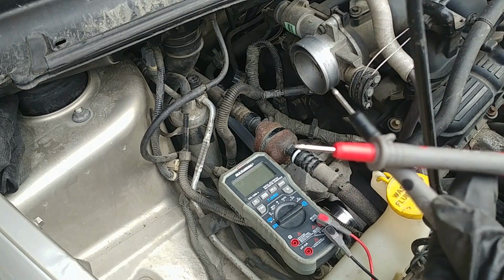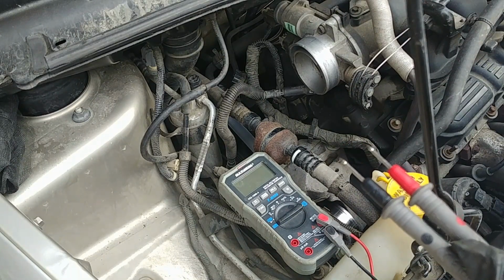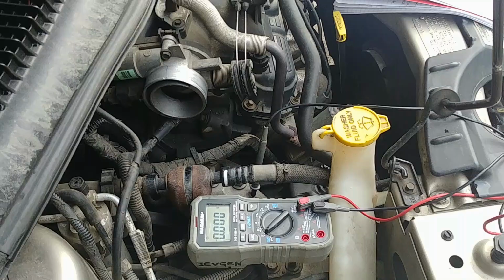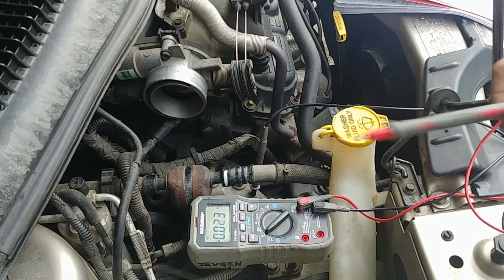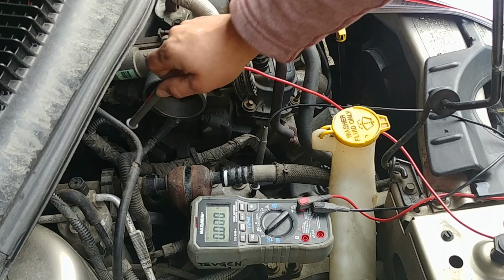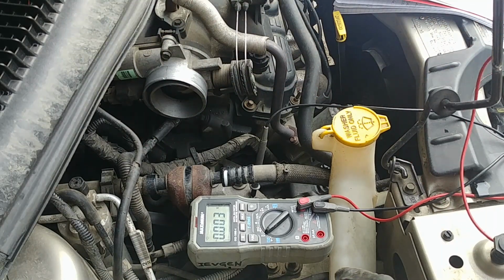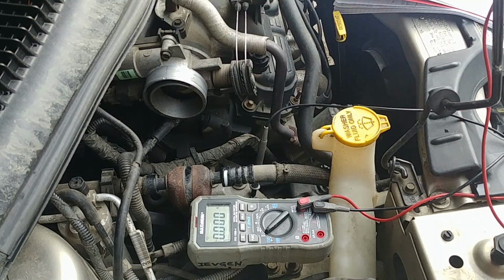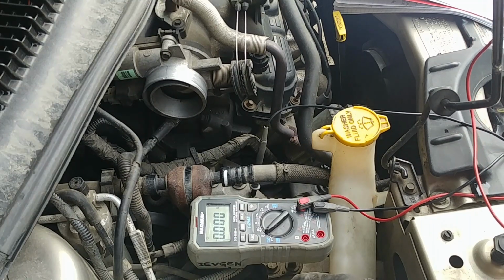And this is where the interesting part begins, diagnostics. If you're not getting voltage at the connector side, it might be a blown fuse due to a short to ground or power, or it can be an open circuit.